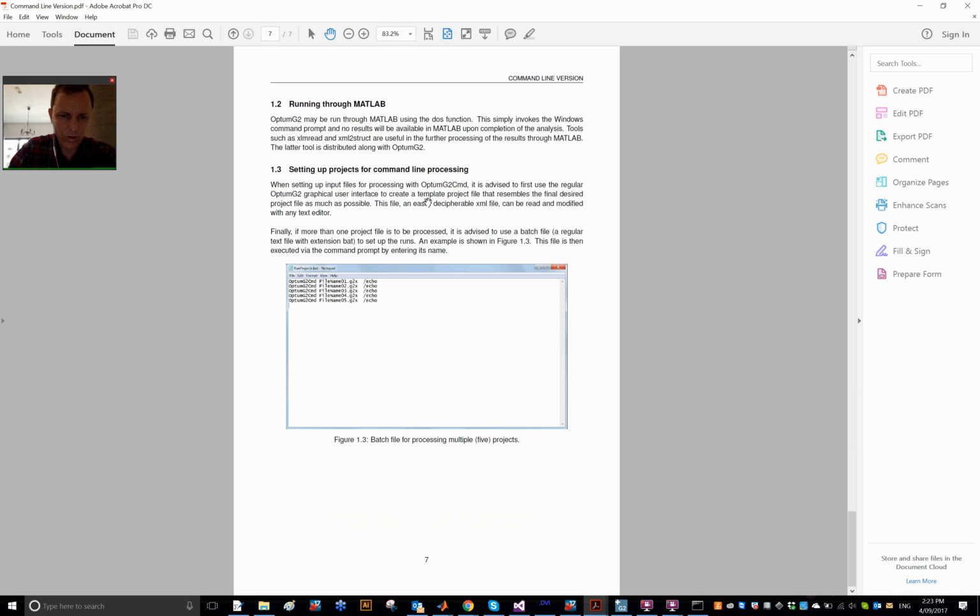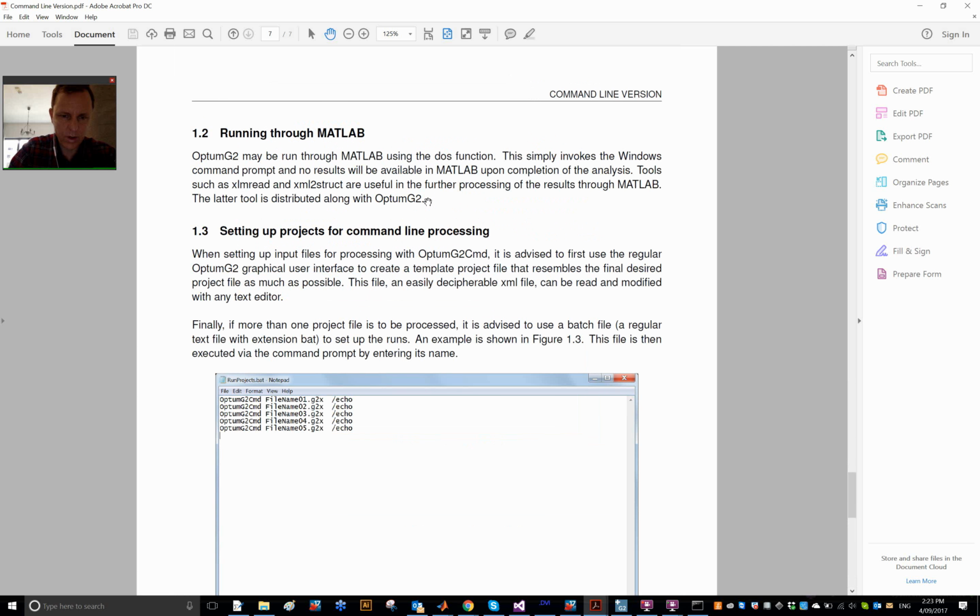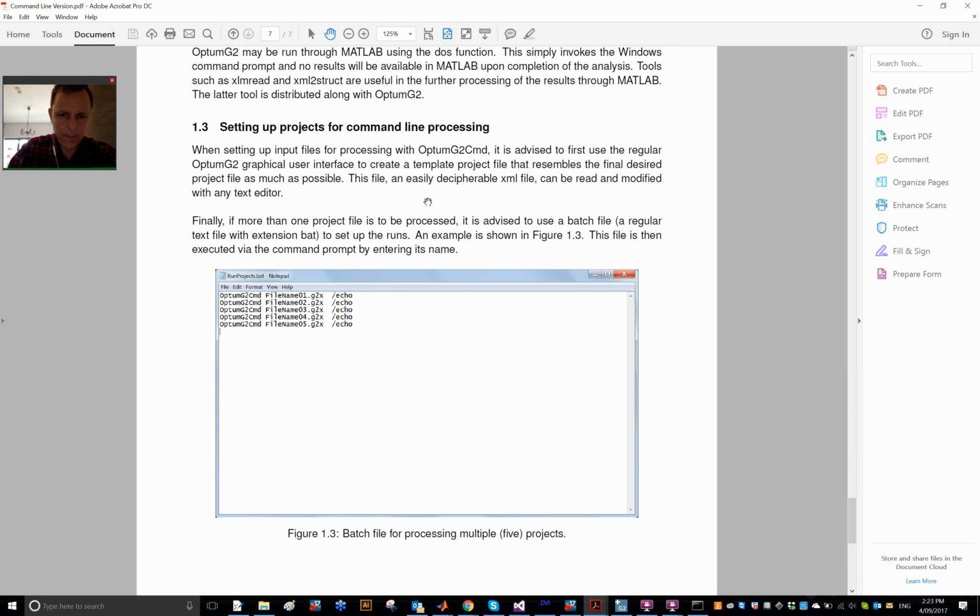And if you want to do this type of analysis for a range of slope inclination angles, what you could do is generate a bunch of input files, and then process these through a batch file, and record the results, and then pick those up and manipulate them, display them as you like.